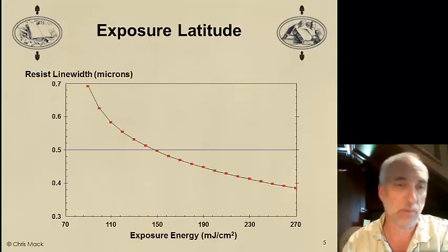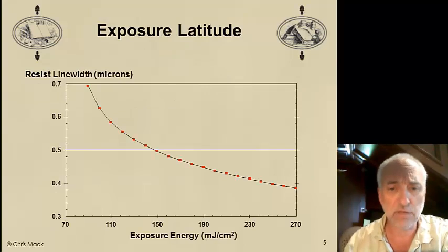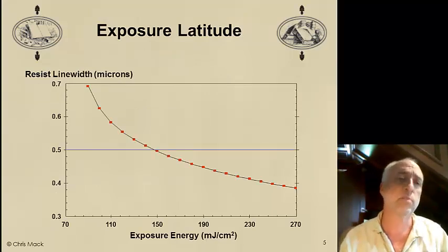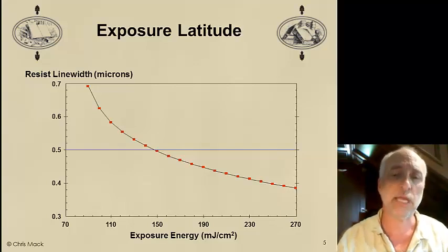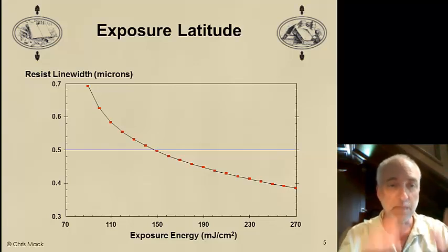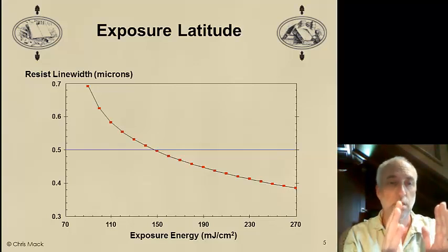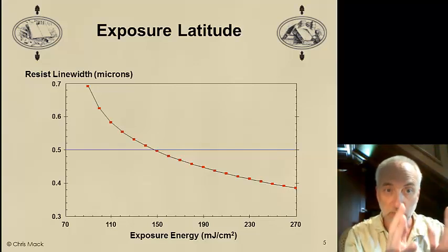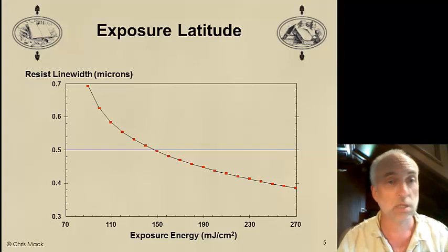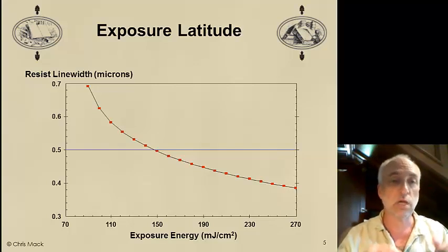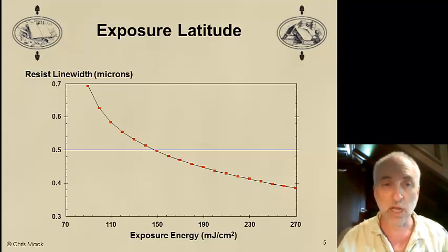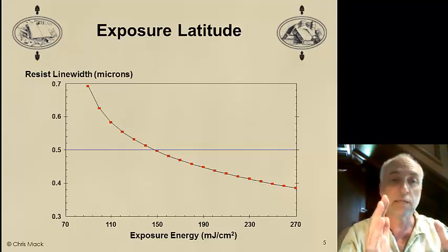Let's take an example. Line width varies with exposure dose. If I have a positive resist, the more I expose the resist, the more chemical change occurs that increases the solubility of the resist. So if I think about a line feature, the line being the region that's unexposed and the spaces on either side of the line are exposed, when I increase the exposure dose, I make the resist in the space regions even more soluble, and the width of that line shrinks.